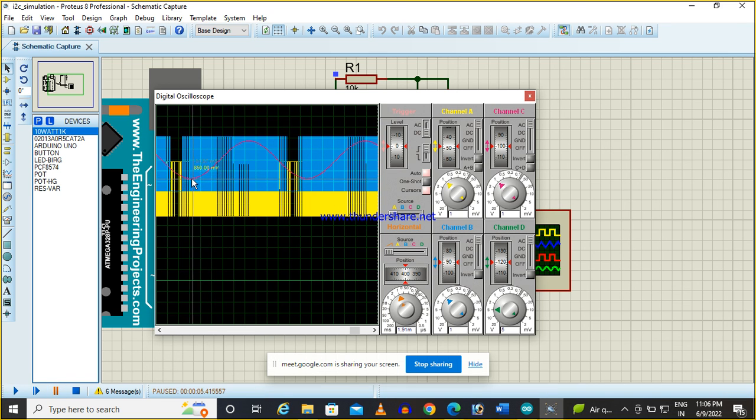Now if you see exactly here, one peak, this peak is at 21.95, meaning take it as 22 millisecond, and here you see it is 0, so it is around 20 millisecond. 20 millisecond is 50 Hertz. So basically we will be giving the pulse in this fashion, and finally at the output we will get the sine wave. This is our main final output of the project.